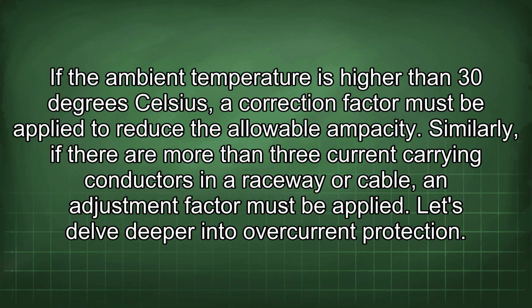If the ambient temperature is higher than 30 degrees Celsius, a correction factor must be applied to reduce the allowable ampacity. Similarly, if there are more than 3 current-carrying conductors in a raceway or cable, an adjustment factor must be applied. Let's delve deeper into overcurrent protection.